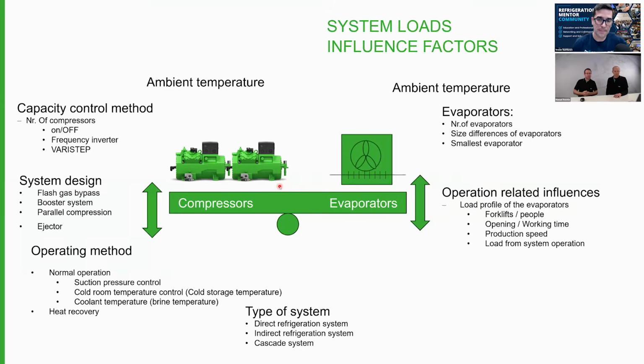The system design itself has also quite an influence on the compressors. If it's a flash gas bypass system, the MT compressors have to deal with the evaporator mass flow plus the flash gas mass flow. So they have to balance the changing requests by the high pressure, but also by the suction pressure. If it's a booster system, the LT stage has an influence. If this is bringing more capacity inside or less, it can be seen as an additional evaporator,